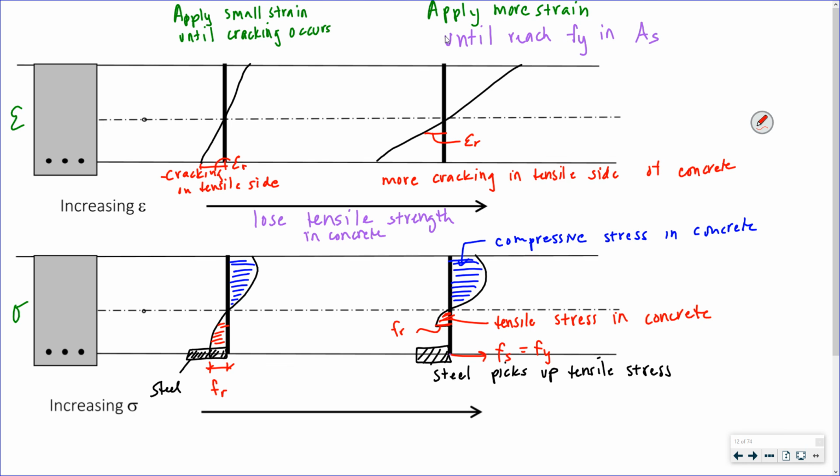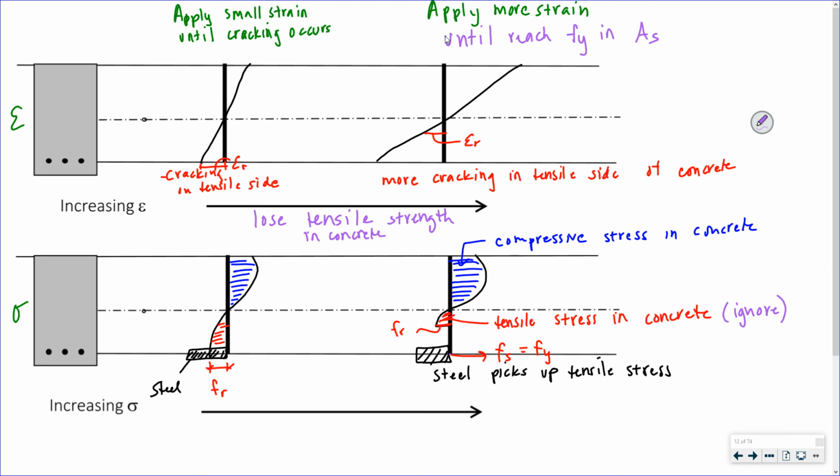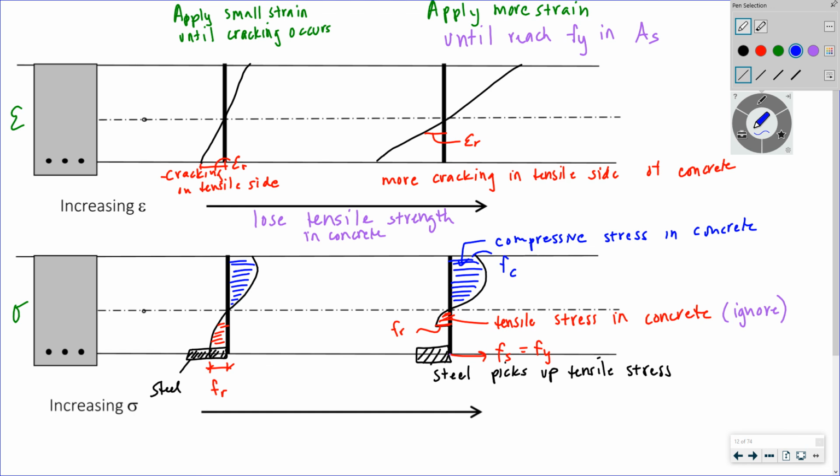We're going to ignore any tensile stress in concrete because it doesn't do us any good. And we're going to call the compressive stress in the concrete Fc.